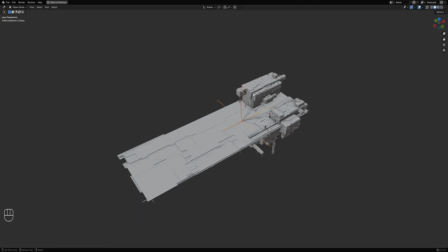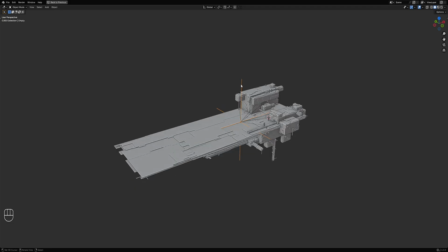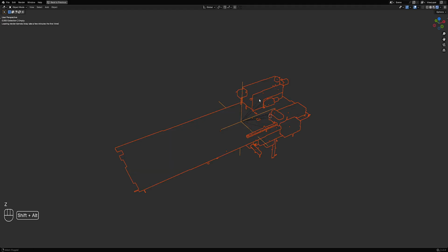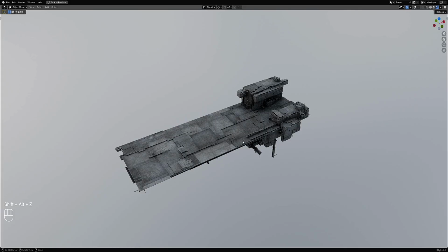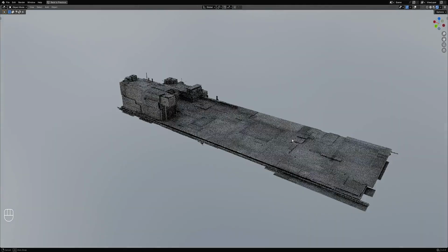But if not, you can just go into this blend file, open it, select this collection, Control C, then open the blend file that you want to copy it to, and then Control V. So you can drag and drop it on any project anytime.